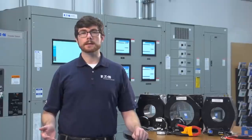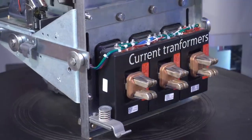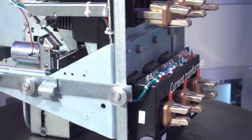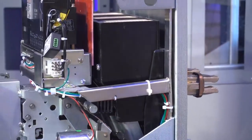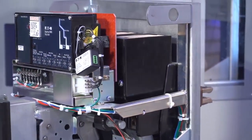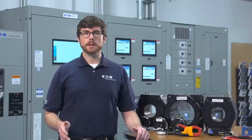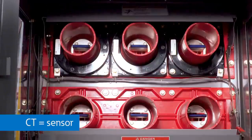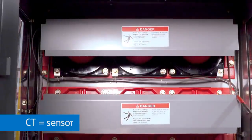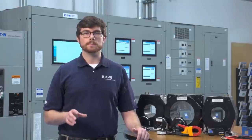On the protection side, CTs can be used in combination with trip units for low voltage circuit breakers and relays for medium voltage breakers to trip the breaker when there are overloads or faults on the system. Many circuit breakers have built-in CTs used to monitor current. As a point of clarification, a lot of people call CTs sensors when they are mounted inside switchgear or circuit breakers, but the functionality and purpose is the same, to get current measurements to a useful level.